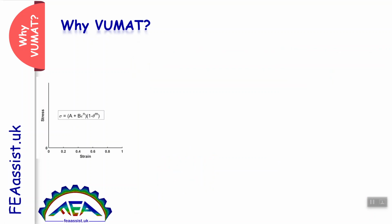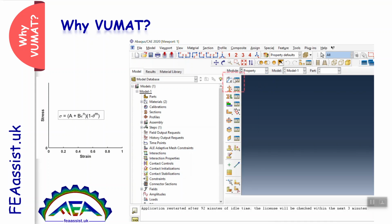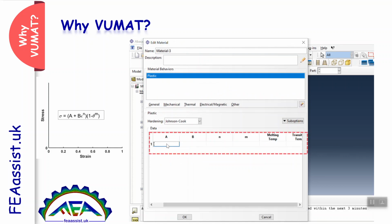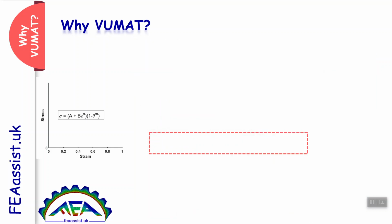If you want to solve your problem more precisely, then you need to have the constitutive behavior or constitutive equation of your material. Your material mechanically obeys some rules. If you have an equation and the equation is included in Abaqus, then you can go to Abaqus again, to property, materials, mechanical, and instead of entering the points, define the behavior. For example, here it is Johnson-Cook. You can enter the parameters and constants of your equations. Abaqus will solve your problem at all points based on this equation. This is more precise because you have an equation.